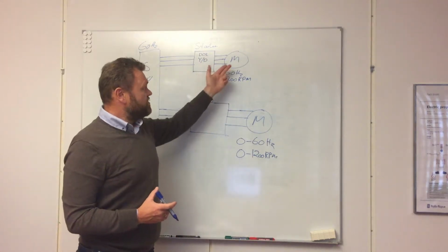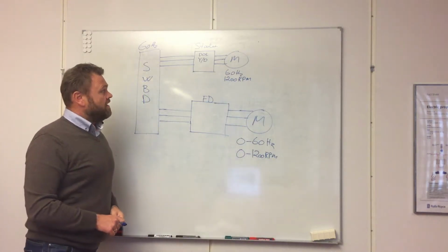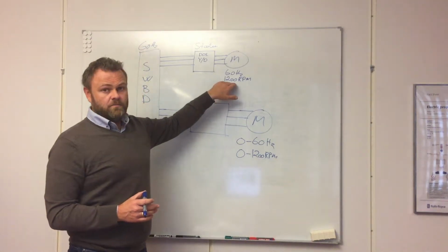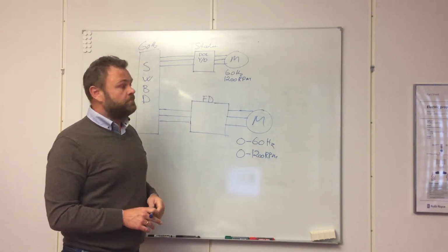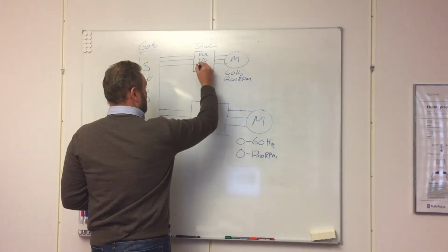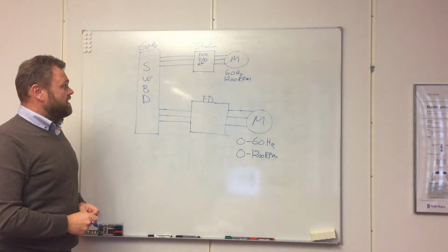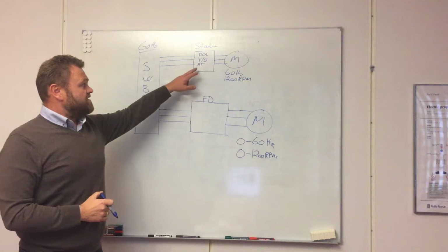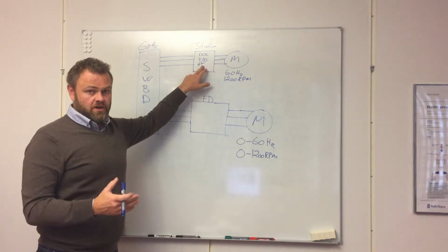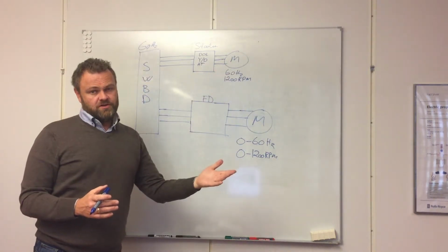However, once it has started, after a couple of seconds, it will be running at fixed speed due to fixed frequency. We may mention auto transformer start, AT starter. It is basically nothing more than introducing a transformer just to give the motor a bit smoother start.